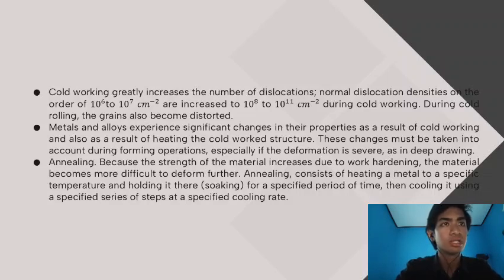Cold working greatly increases the number of dislocations. Normal dislocation densities on the order of 10^6 to 10^7 per cubic centimeter are increased to 10^8 to 10^11 per cubic centimeter during cold working.